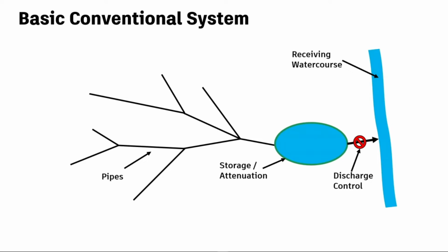And then finally, at the end of the drainage system, you'll find outfalls which discharge stormwater into natural bodies such as rivers, lakes, or the sea, or existing systems. Outfalls are designed to allow control over the rate of discharge into whatever water body it connects to. In the UK, the majority of new developments will have a limit placed on the outfall's discharge.